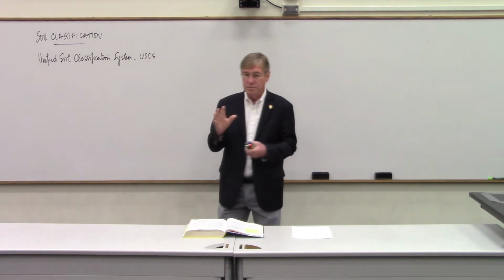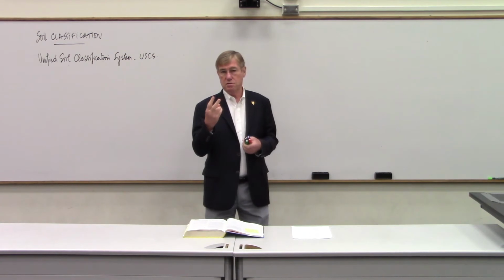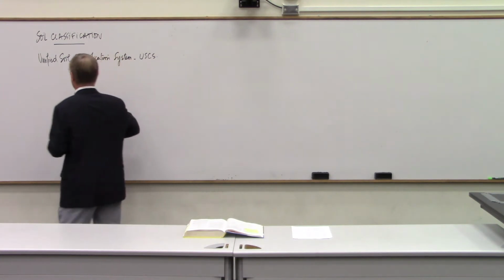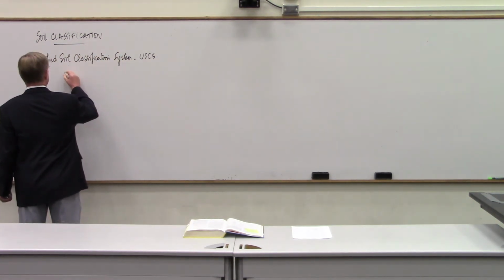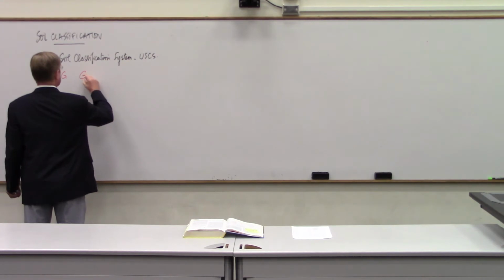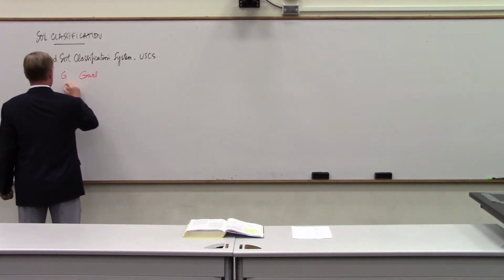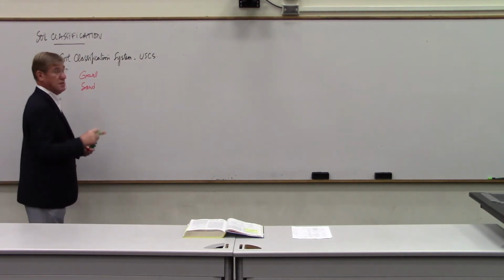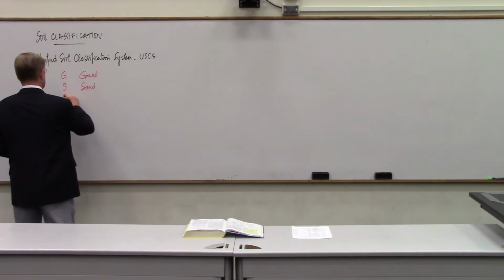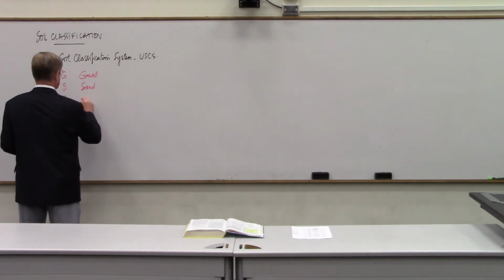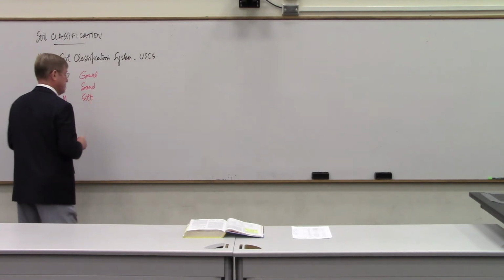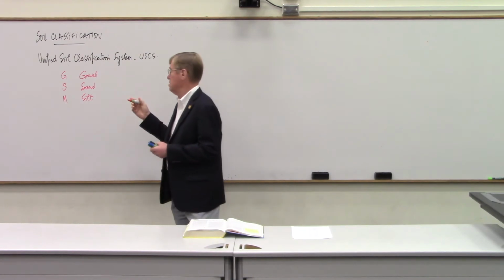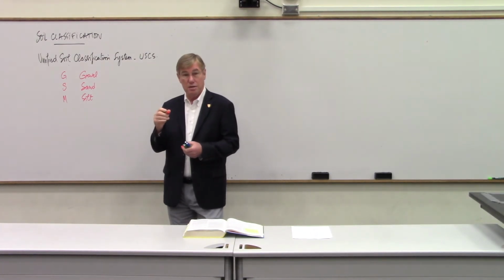We're going to aim to use two letters to classify the soil. So the first letter will be either G for gravel, S for sand, and silt is also S. So we had to use a different letter, and for silt we're going to use M, because I believe silt is mjäla in Swedish.